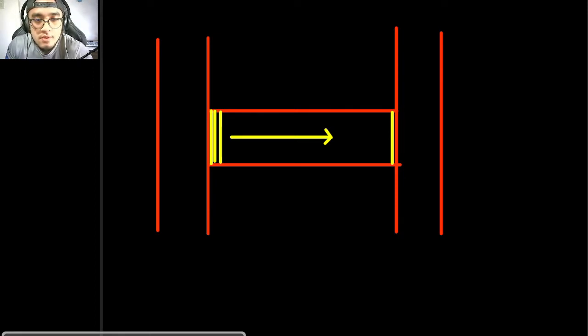So what we typically do in manual computations is that we would be getting one critical portion of a structural member, and that is to be our basis in most of our designs. That right there is a very conservative approach, a very fast approach, but not really the most economic approach. And STAAD.Pro is a program that will help us analyze finite elements without compromising our time. With the help of your computers and STAAD.Pro, you can now solve for the stresses of every element in your structure, may it be this element right here, this element right here, and whatnot.